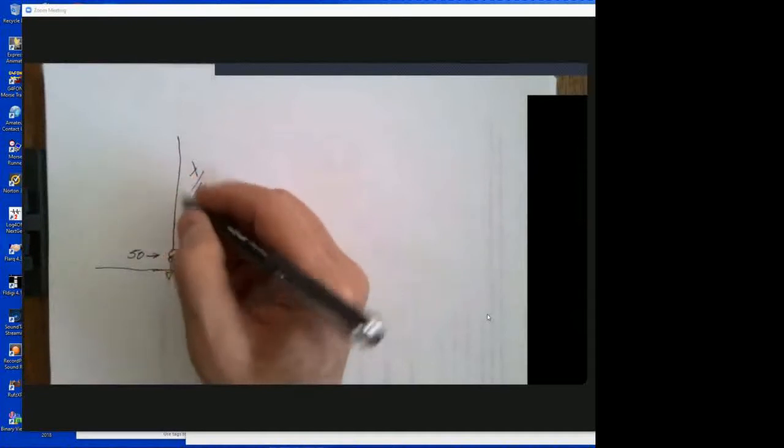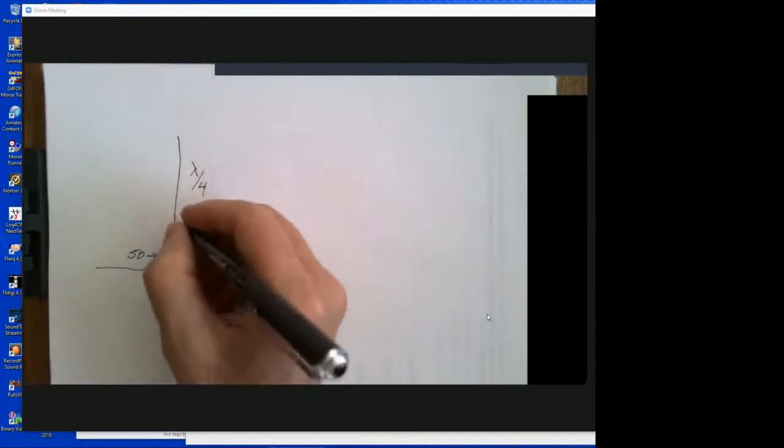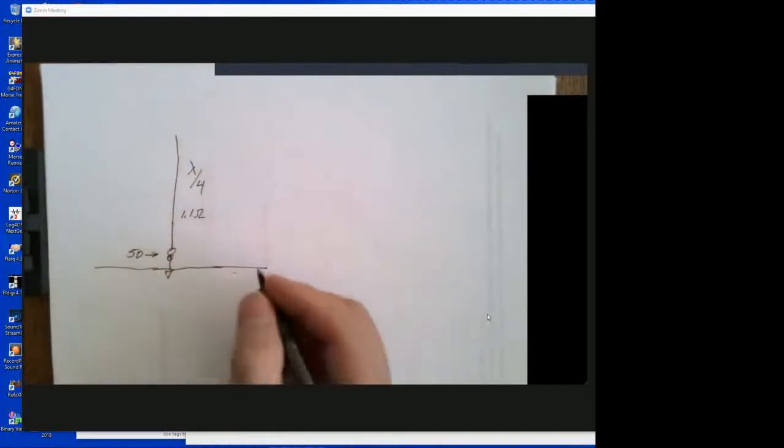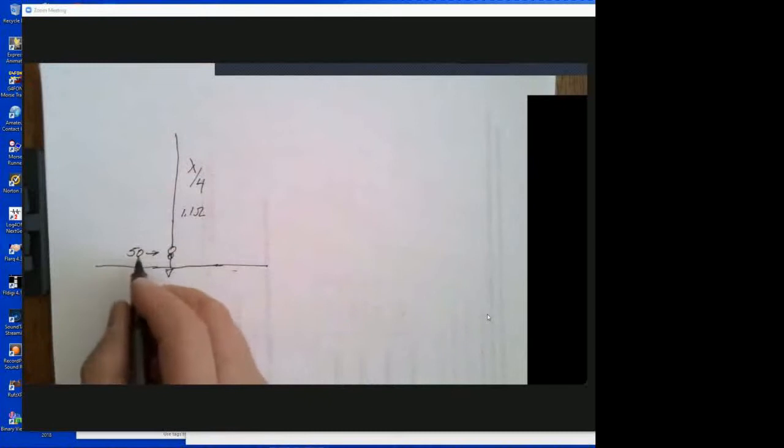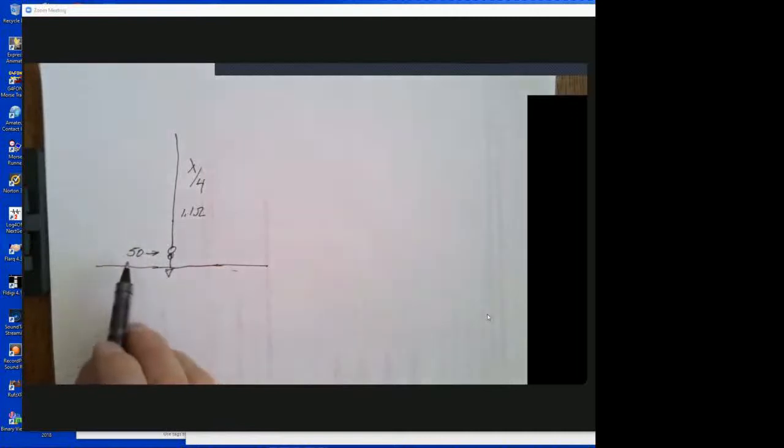The question is, is it really significant? Well, it turns out if you had your 12 gauge wire, you get about 1.1 ohms for a 40 meter wire, if you made this a wired vertical. Let's look at how this would be affected. We would look at the power being dissipated by the 50 ohm resistor, and then the total power being dissipated by the system.